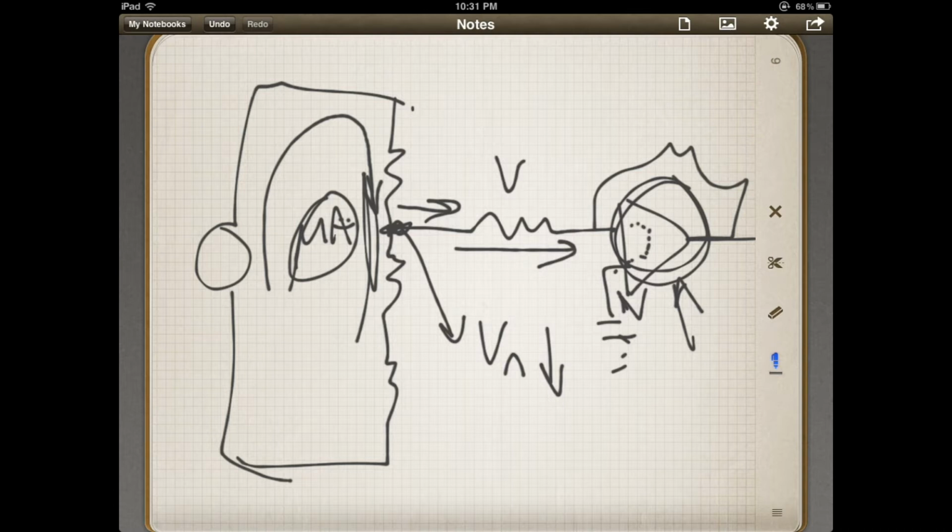You can basically rob some current from this totem pole stack and not affect the voltages across your components. So that's a good rule of thumb to remember when you're choosing op amps, and if you're doing any kind of precision work where you need the voltages across these resistors at certain points in your system, you want those voltages to be preserved and maintained.